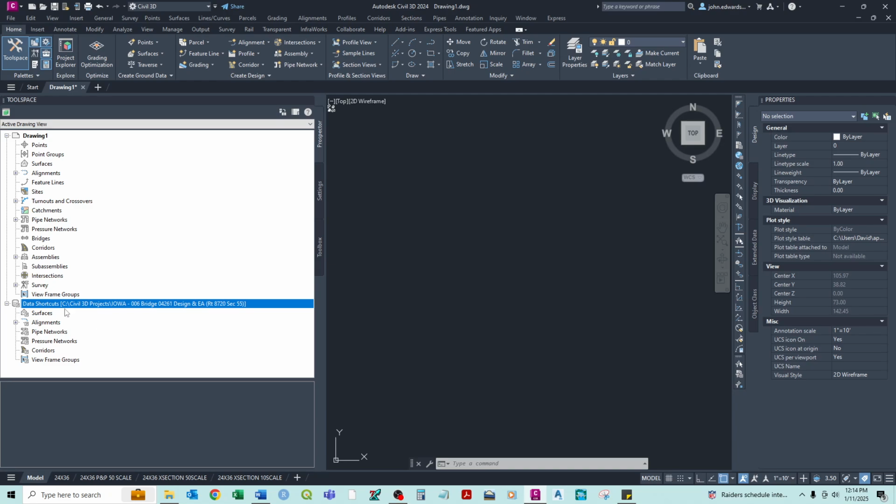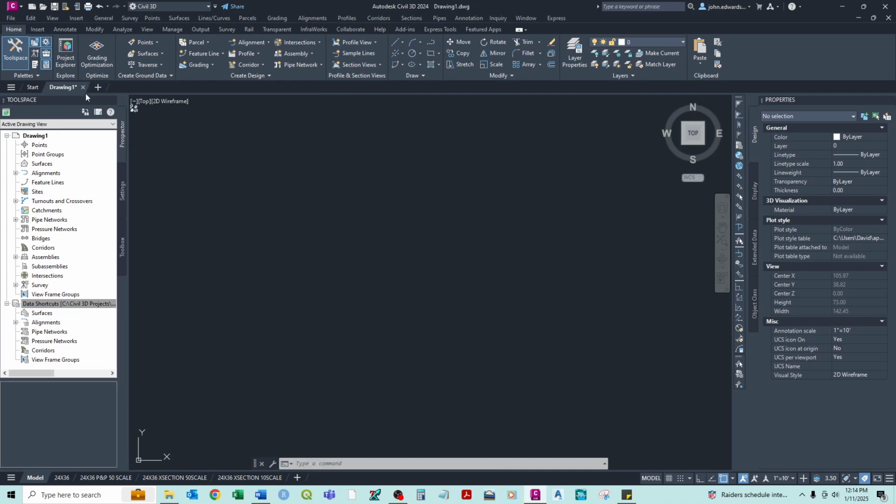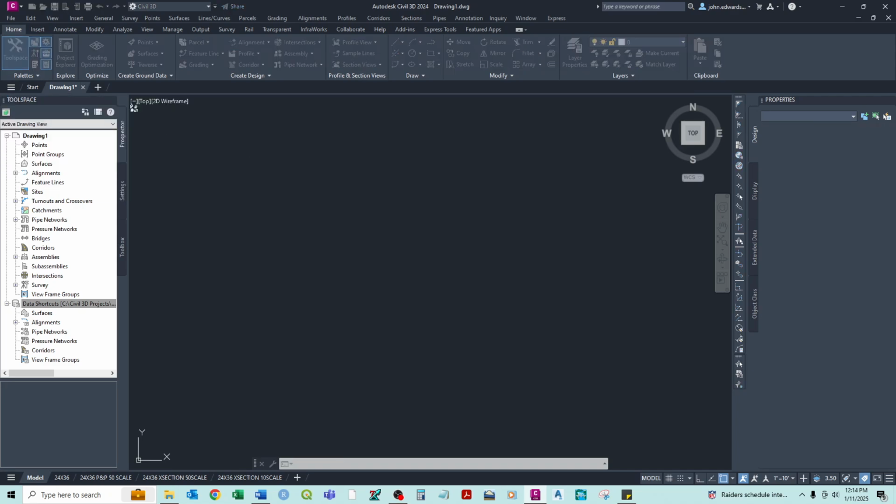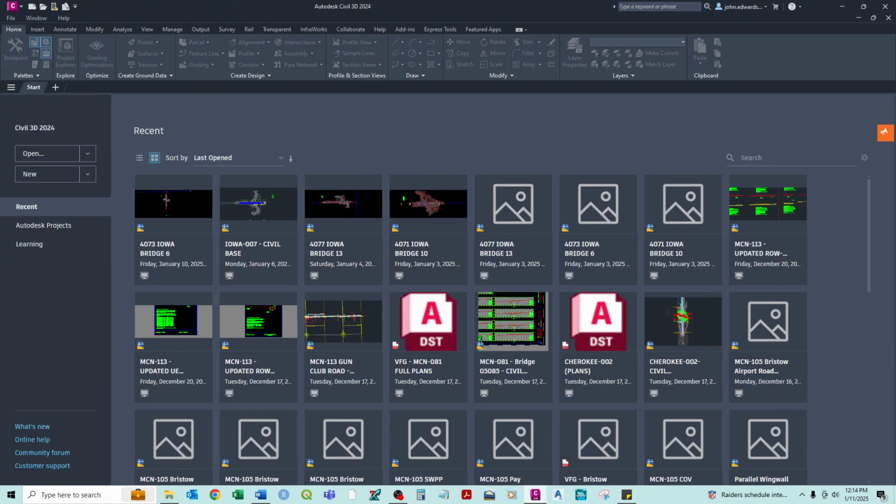Essentially, what you'll do is right click and then associate this project to the current drawing. That references this, so any object you create will dump into that shortcuts folder as long as you assign it. So that's the first step in starting our new Civil 3D project.